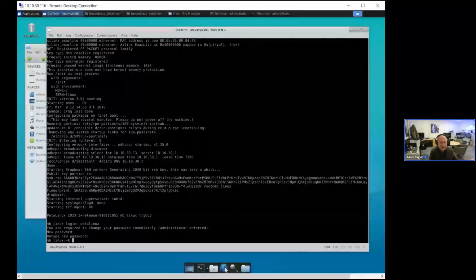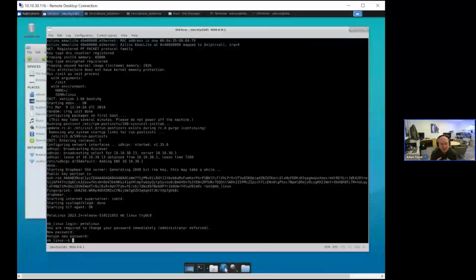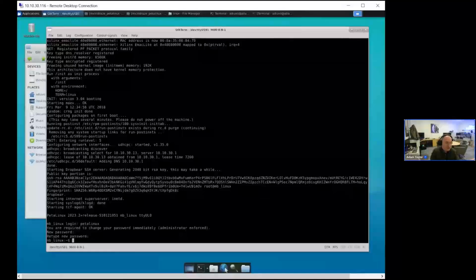So I'm like, that's good. It didn't quite pick up and work from Petalinux because it needed to be there from power on, but it gave me the ability to test it. My point here is the flexibility, the ease of use. I don't need to write a huge bare metal application to do this. I can just use Linux tools like i2cdev and just read and write the registers.